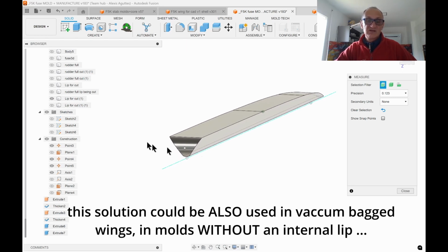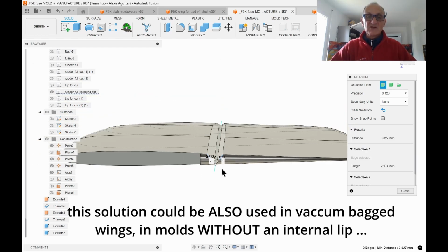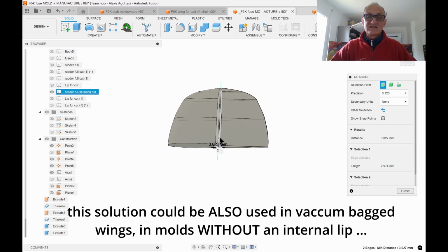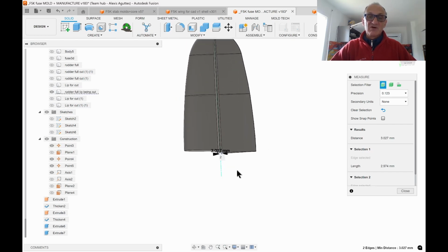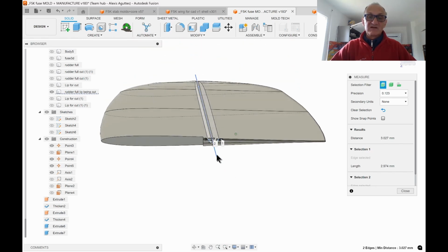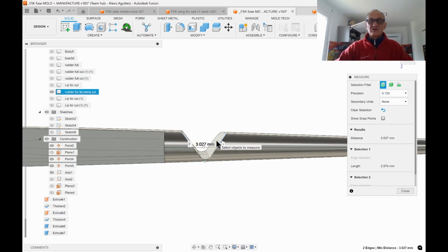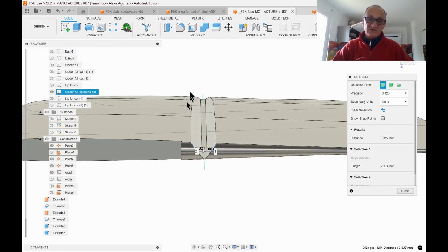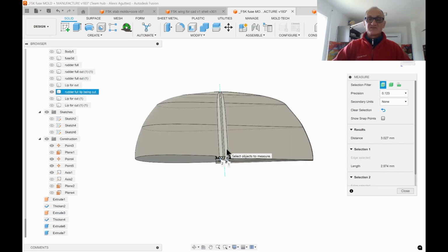an elegant solution because additionally you could change the angle. So if necessary, I realize that I don't have enough input control on my rudder. Maybe I need to open the rudder a little bit. I will make another lip with a more open angle. And what I have to do is just change the lip and remill another set of core. To finish, I just need to cut this one, then I need to mill these two cores separately and put all of it with the lip into the mold.